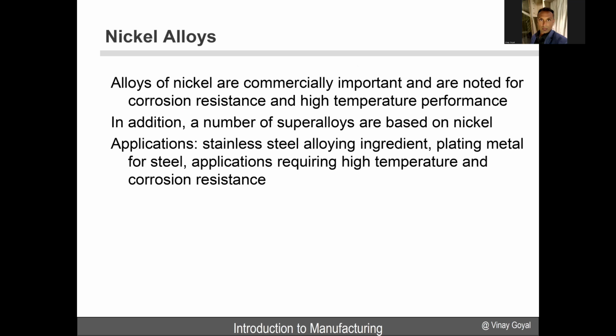So alloys of nickel are commercially important, and they're used in a lot of different applications, and we call them superalloys. A lot of superalloys are based on nickel because they work for high temperature performance and great corrosion resistance, and so superalloy is the appropriate name for them. Applications: stainless steel alloying ingredient there, plating metal for steel, and applications like engines, like I said before.